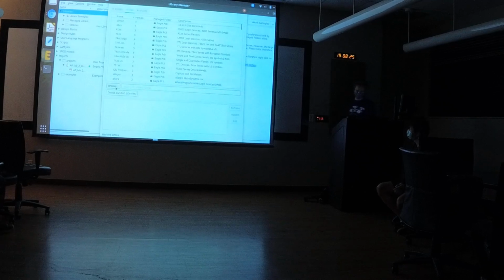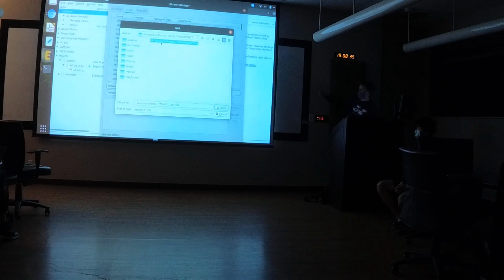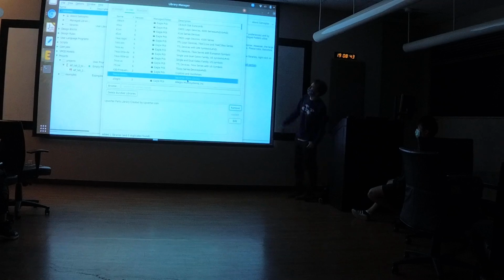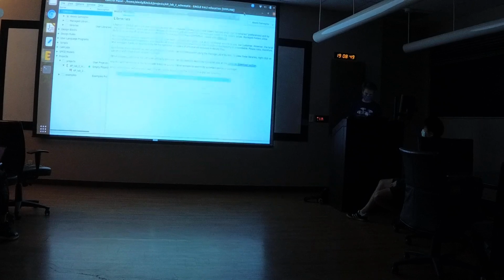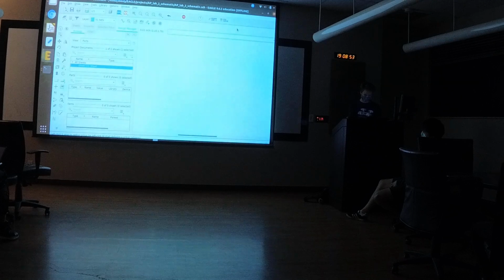Right. So right here, if I want to add something, I hit Browse. I go to, I don't remember where I saved it. I think it was in Eagle. I see it. Right. So you see it pops up the .lbr file. We hit Open on this, and you see how this part just popped into my list of libraries. So I don't have to hit Save or anything. I just hit Close.